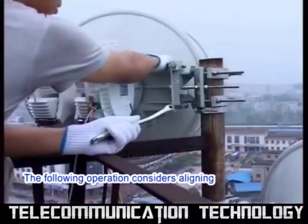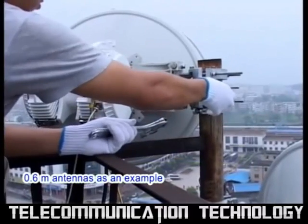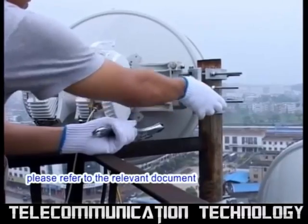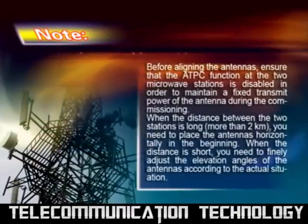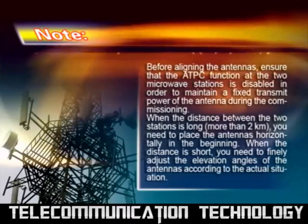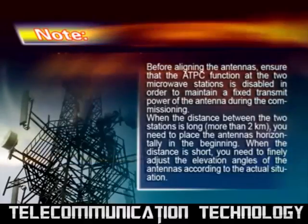The following operation considers aligning 0.6 meter antennas as an example. When the antenna is of a different diameter, please refer to the relevant document. Note: before aligning the antennas, ensure that the ATPC function at the two microwave stations is disabled in order to maintain a fixed transmit power of the antenna during the commissioning.